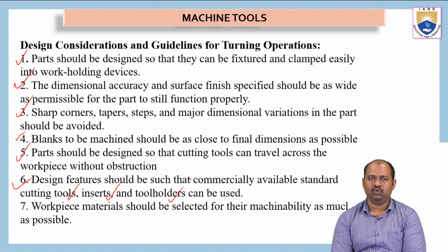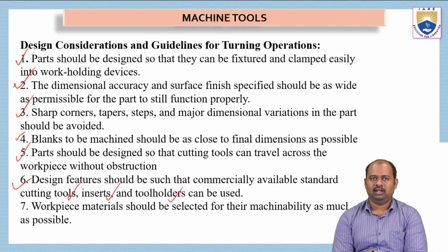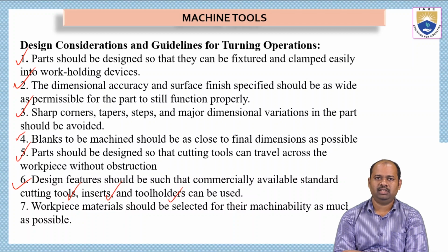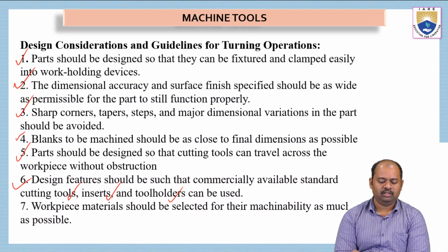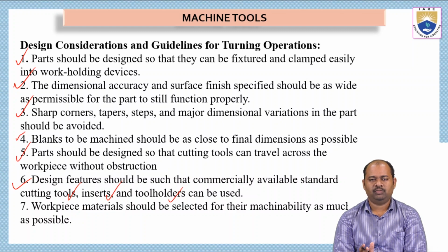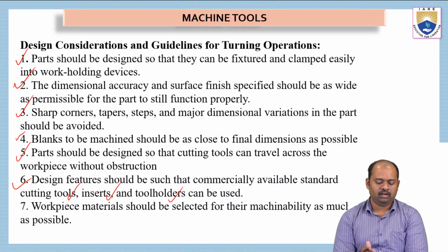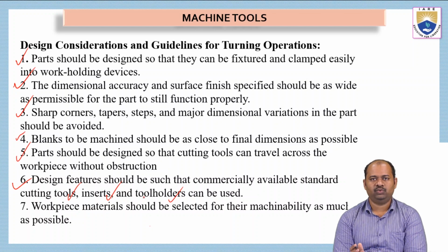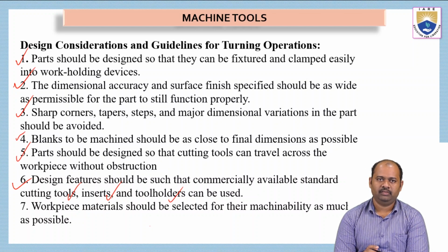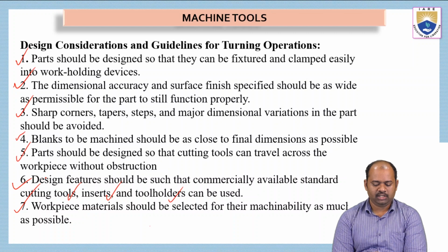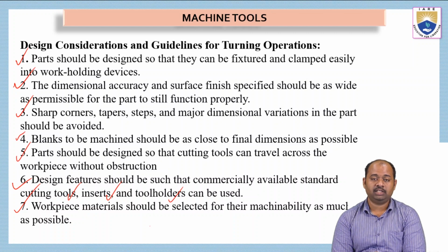The design can be done only within the standards of the industry. Otherwise, the cutting tools may not be suitable for your workpiece metal, or inserts and tool holders may not be suitable for your workpiece design. And then we have workpiece materials should be selected for their machinability as much as possible.